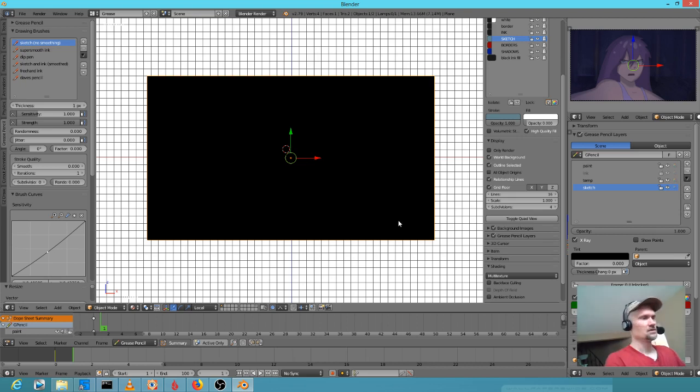What I know works, and by the way, I think we'll have to check this, but this is something you might want to be aware of. In the shading, and by the way, you open and close this panel with the N key, it could be that the shading needs to be multi-texture as opposed to GLSL. You might want to experiment with that.